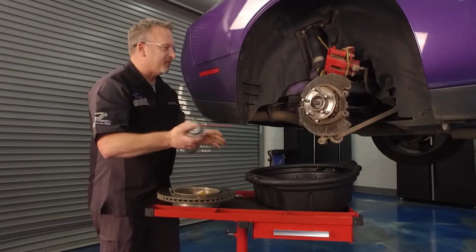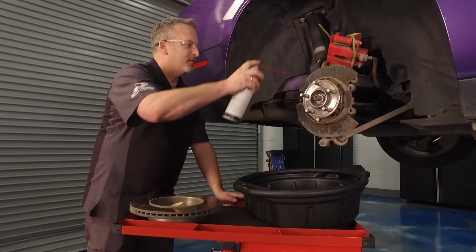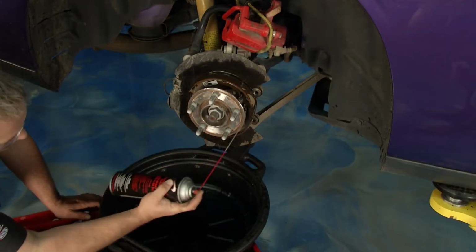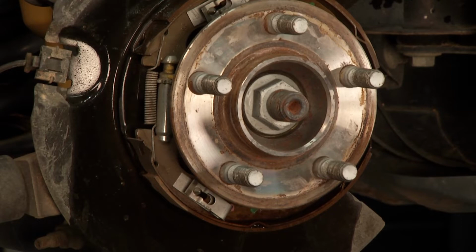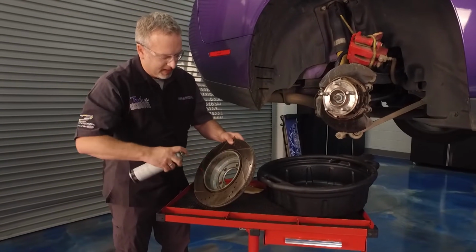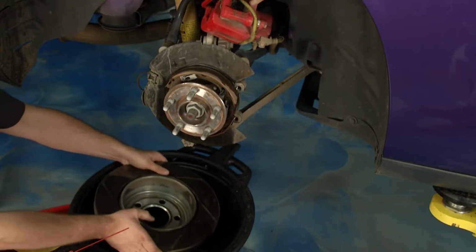And the final step, of course, we want to take some brake clean. Make sure you got something to catch all this debris underneath, by the way, as we have here. We're going to take our brake clean, give it a nice spray and get all the junk off of here. Do the same thing on our drum inside our disc, and we will be good to go. That one's dripping there, so I'll put it there.